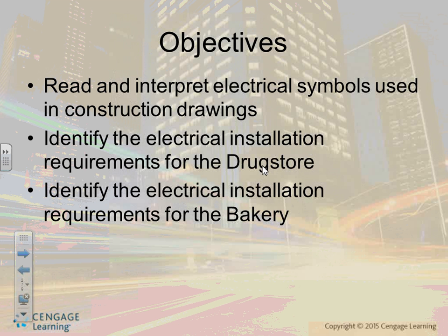If you guys look at the first page, page A1. A1 says basement floor. You guys know how to read the blueprints. It has a label. If you look at the bottom, commercial building, A1, sheet 1 of 10. Can you guys see what says sheet 1 of 10? A1 is a drawing, the basement floor. What's the scale? Everybody can see the scale? In the bottom right, the scale is 1/4 to 1. So that's how you read that one.